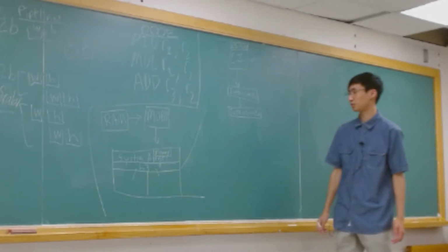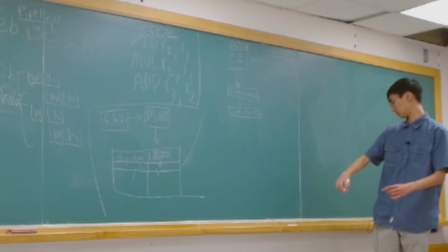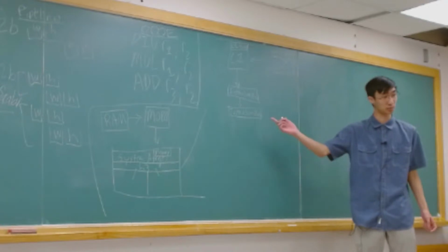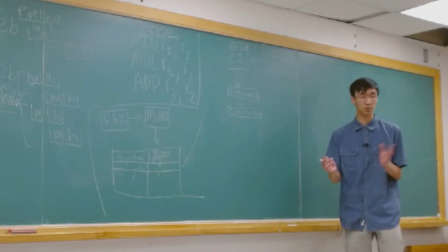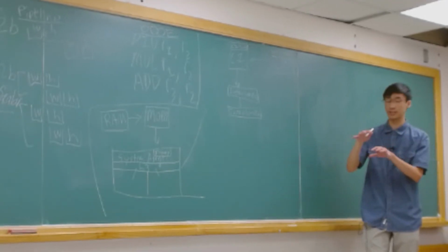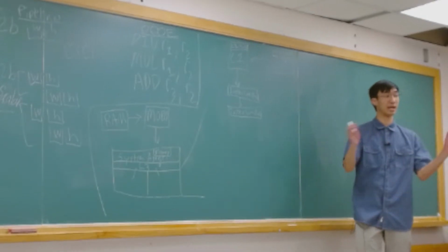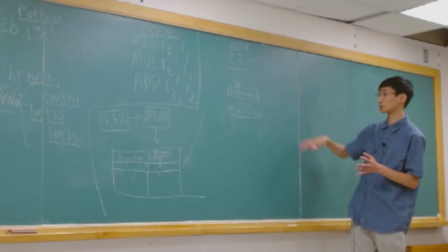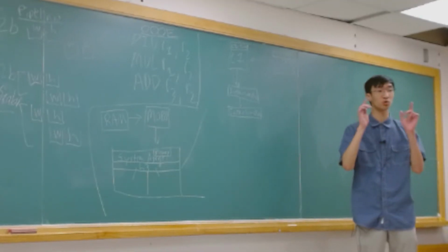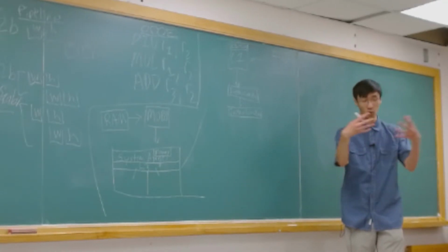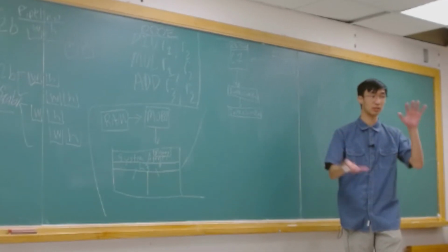This instruction queue holds 50 instructions-ish, and then we'll do an optimization here. A couple of our instructions are always next to each other and can also be executed together. So instead of taking up multiple entries, as I said, this thing holds 50 entries. That's going to be the same for a lot of these components I'm going to be drawing: there's going to be a number of entries you can put into buffers. Preferably, instructions that are always going to be next to each other should become one instruction.